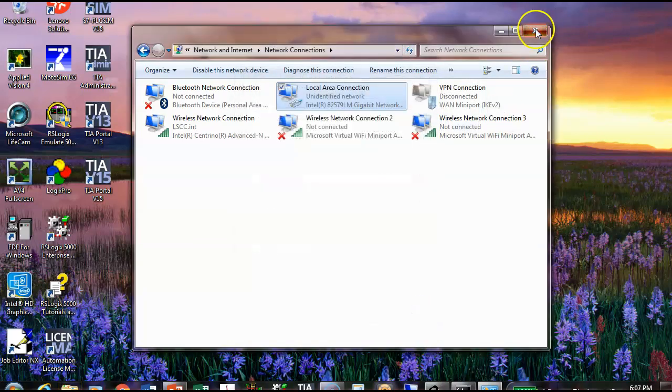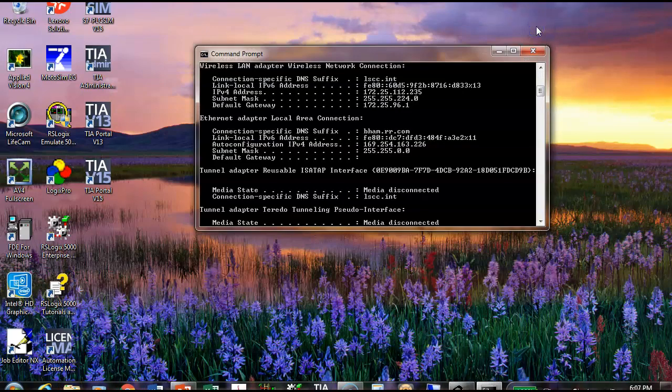So that means I hooked my computer up. This is the first time I did it. This guy doesn't have a battery in it, so don't unplug your PLC down there, because we'd have to do this again. If I turn this off or unplug it, it's going to lose the IP address because of the battery. Most of these things have a little slot where you keep a battery. And that's one of the things you might lose if you're running Ethernet IP. If you lose that battery, you might lose your what? Your IP address.